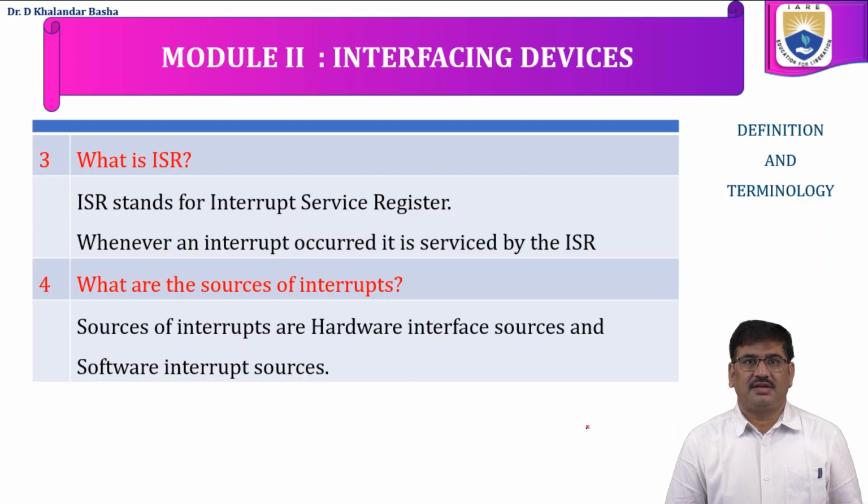What is an ISR? ISR stands for Interrupt Service Routine. Whenever an interrupt occurs, it is served by executing the ISR. If the processor is given an interrupt request, the processor terminates the main program it was executing and goes to the ISR. That subroutine corresponds to a particular kind of interrupt.